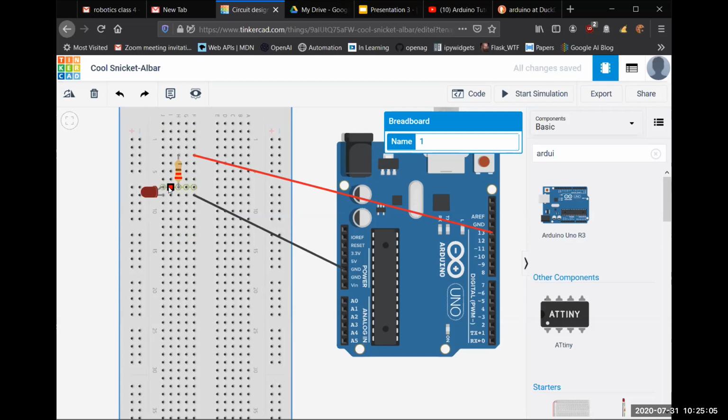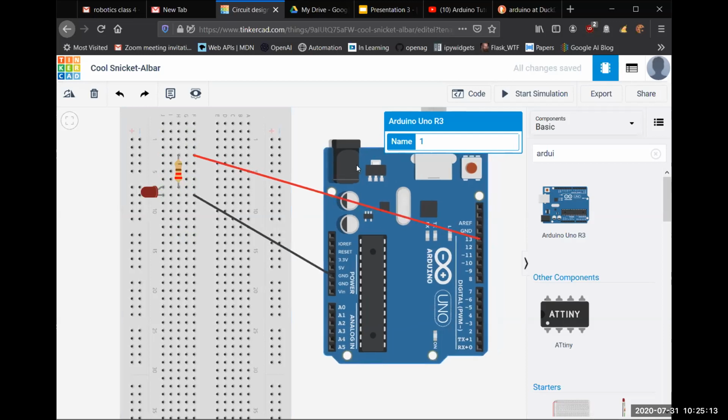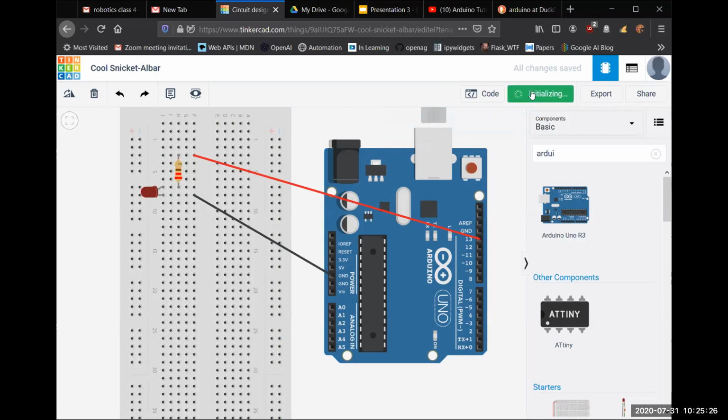The other thing you do is make sure you push it in completely. And before you go further, the best way sometimes is to upload the program and just test one LED first. So you test this and connect your Arduino to power. If you have the right program, this is what will be happening: it will be going on and off, on and off. Okay.